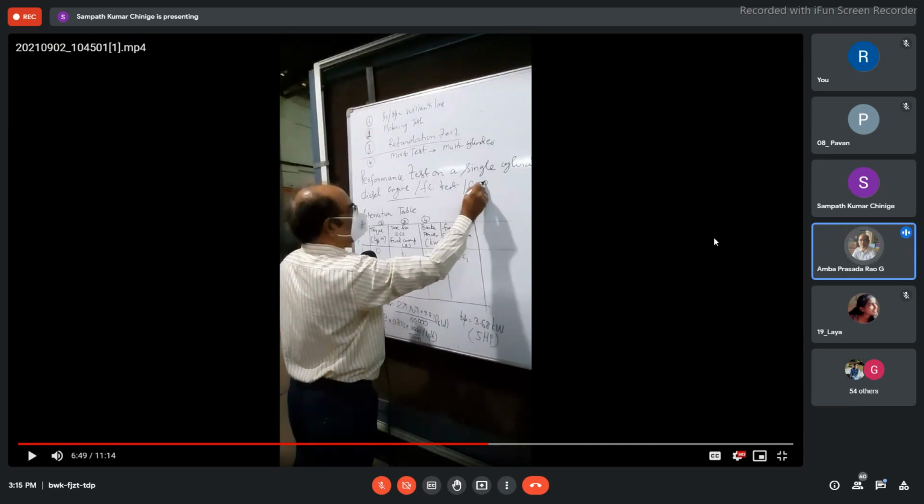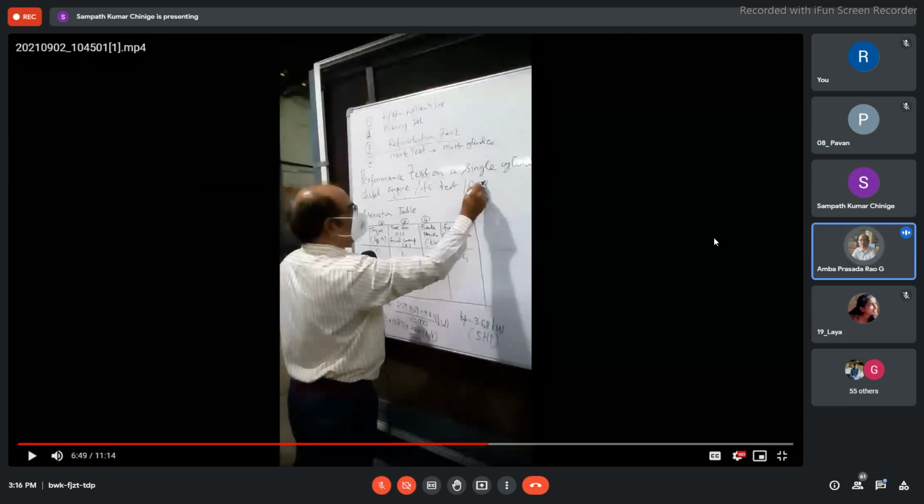So you know pretty well that it is a 4-bar chain mechanism, no? So a crank slider mechanism where we have volume as a function of theta, from top dead center to bottom dead center. It is traversing like a crank slider mechanism you have done in kinematics of machinery. So some conversion is there from theta to volume or vice versa. So likewise, you get what is called the PV diagram, very popularly called the indicator diagram of a particular engine.